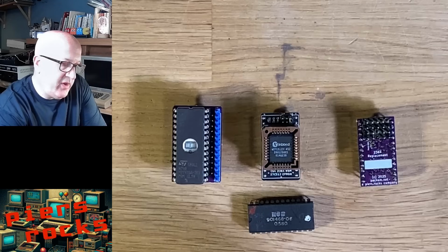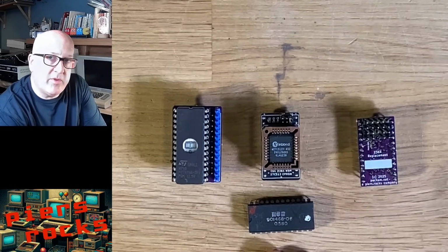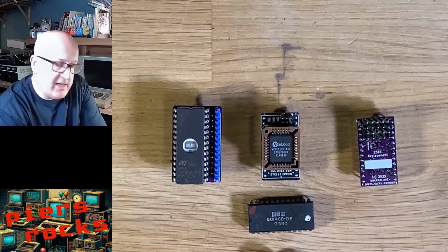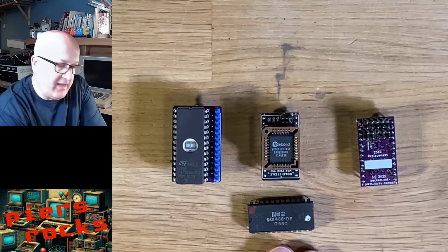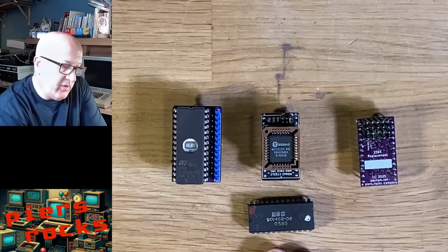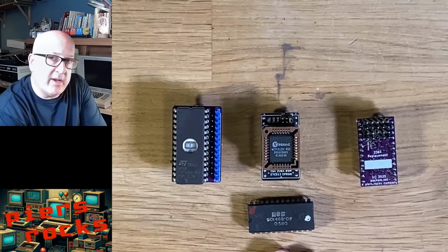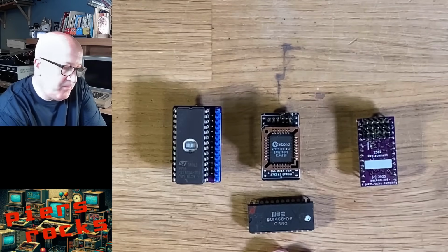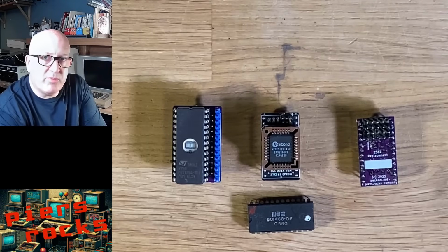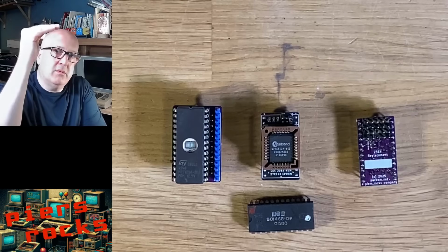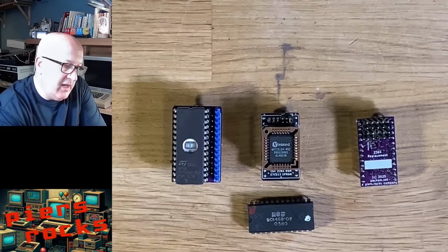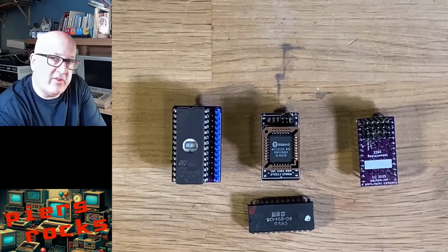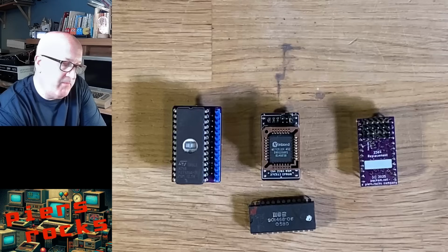Now, chip select line is how the system indicates to a particular ROM or RAM chip that it should be active, that it should look at the address lines and place data at that particular address within it on the data pins. If you had more than one of those chips selected simultaneously, they'd both be writing to the bus and garbage would result. The chip select line behavior was mass programmed at factory, so they could either be active low or active high. And each different chip select line on the 2332 and 2316 could behave differently, so you could have any combination. That means two different chip select combinations on the 2364, 4 on the 2332, and 8 on the 2316.